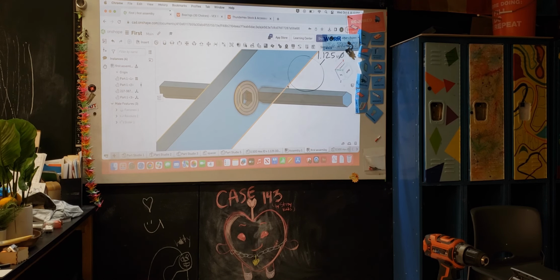What happened here is that the slider mate works so that it only slides on one of the axes. I think right now it defaults to the z-axis, right? No, it'll default to the perpendicular of the two faces you mate. Yeah, it's kind of an odd feature.